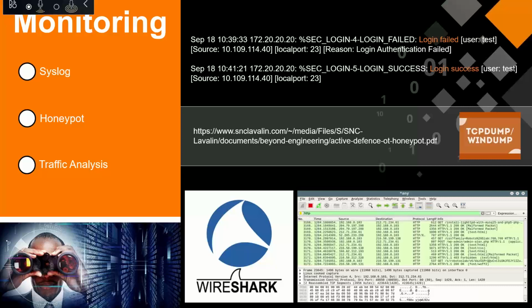With all these great capabilities of Wireshark in mind, please do realize that it can still not be compared with commercially available tools that sniff the network and find software versions and match these against the vulnerability database, or provide an inventory overview of actual device types, makes and models, and automatically alert on illegal traffic flows or deviations from a baseline. And the same really goes for tcpdump or WinDump, although these are great tools that can quickly raise the security level of your industrial network. It will still require some manual effort. But if you're up to that, go ahead and take advantage of it.